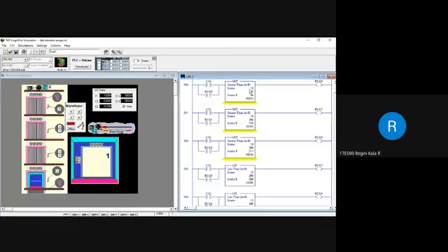Here in the first position, the source is I:5, which is nothing but the encoder. This encoder handles all the lift positions. And in the second source, I will write the value 44, which is the value when the motor is in the fourth floor. Here in I:5 it shows 002CH in hex, and in decimal it is 44. So source B is the value of the lift position at each level. For the fourth floor the value is 44.